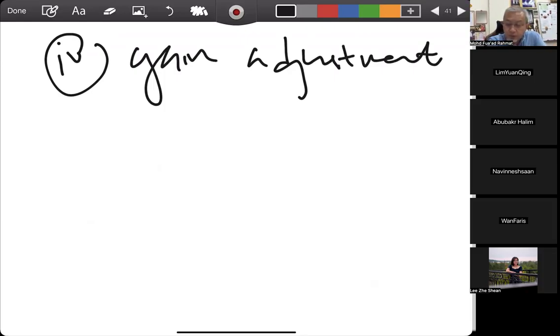The magnitude needs to be reduced by 30. To increase the range of stability of the closed system, the gain margin needs to be increased by 30 decibel. Okay, using the gain adjustment technique, determine the gain K to achieve the requirement. Okay.